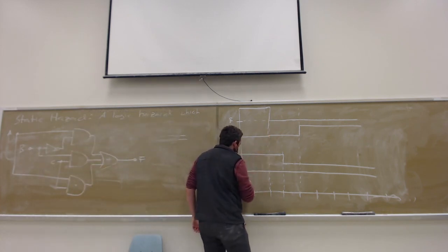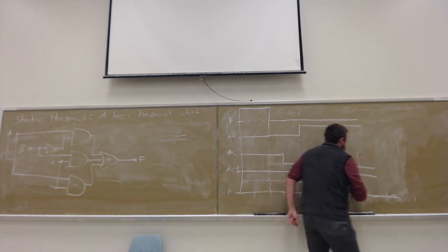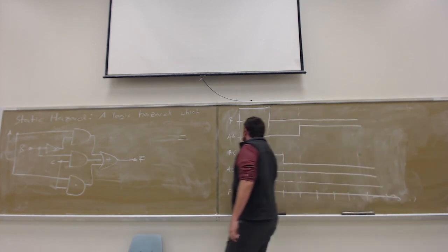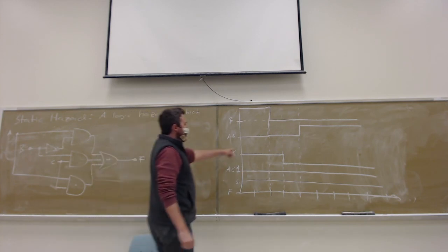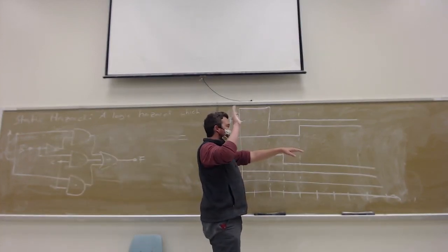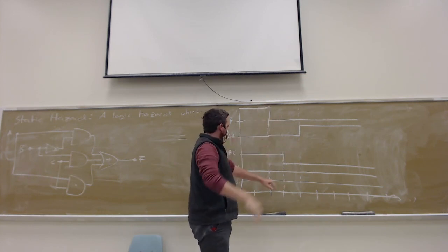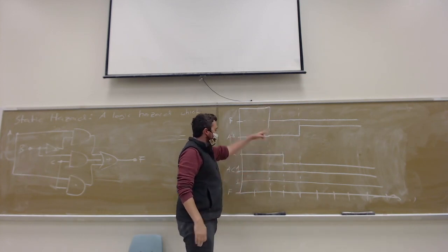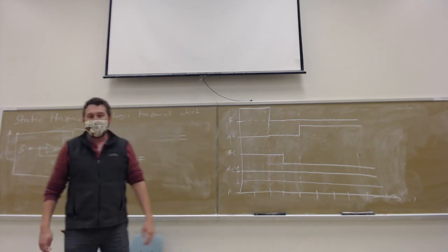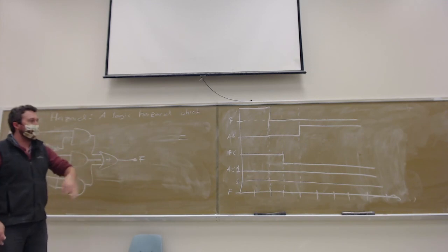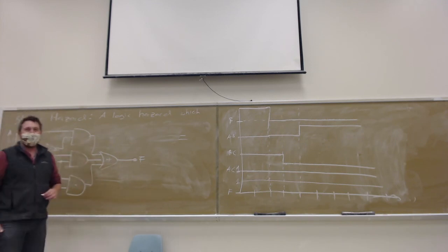All this other changing has no impact on F. So we never get that hazard. The switch from one input combination to the other should have been 1 to 1. Adding the consensus term removes the logic hazard and keeps it at 1. By building consensus terms back into the circuits, you prevent the logic hazards from happening.